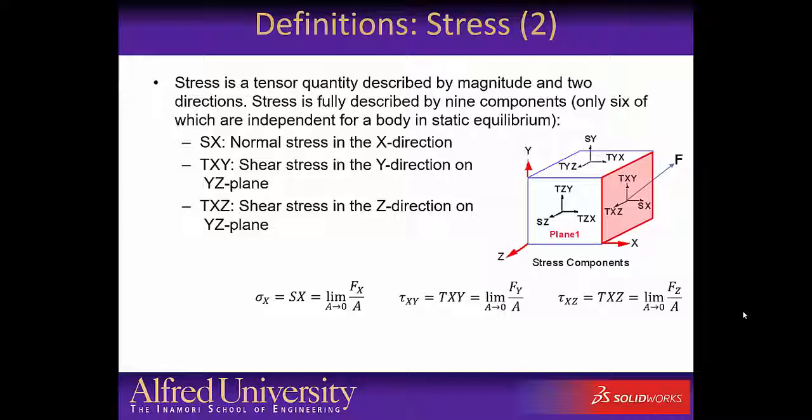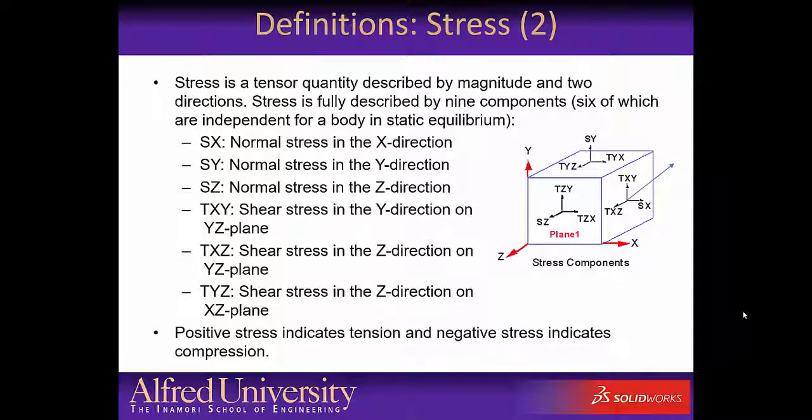Similarly, if we were to take the limit of the z component of the force divided by area and look at the limit as that infinitesimal area goes to 0, we can define the shear stress acting in the z direction on the highlighted plane. So as shown, we can define three stress components related to the three force components that could be described as acting upon this plane.